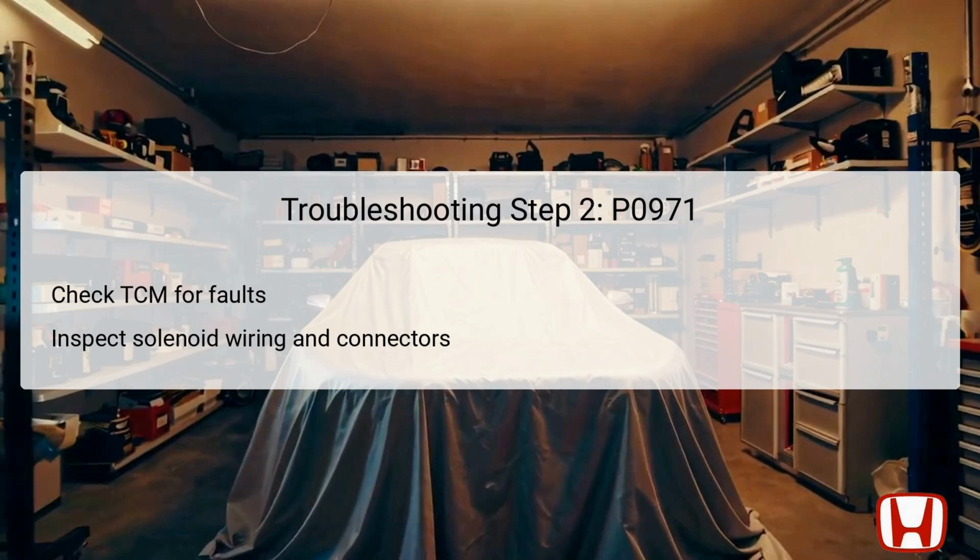Damaged, corroded, or loose connections can lead to variable current readings, which may trigger the DTC. Attention should be given to continuity tests to ensure that electrical signals can travel freely without interruption. If any abnormalities are discovered during these checks, repairs or replacements should be made to restore proper electrical flow. These actions will help isolate the issue affecting the solenoid circuit and potentially eliminate the DTC.